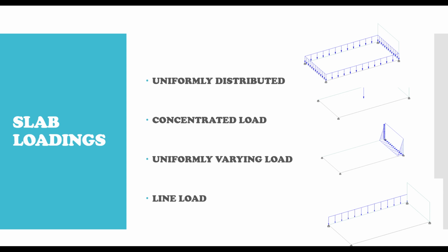But practically, what are the kinds of load that we consider generally on a slab, especially when we are referring to building structures? One of them is the dead load. This dead load is also known as the permanent load. It comprises the self-weight of the material. Let's say your slab is made up of concrete. That means the self-weight of the concrete itself.